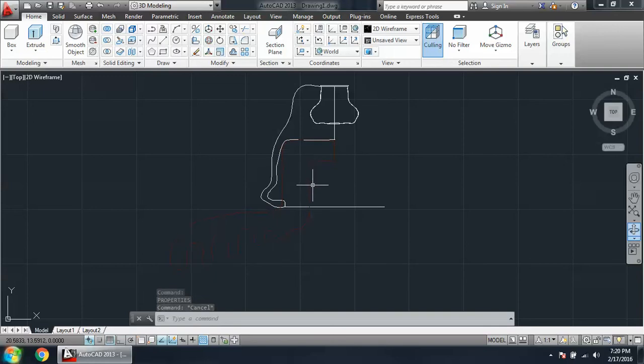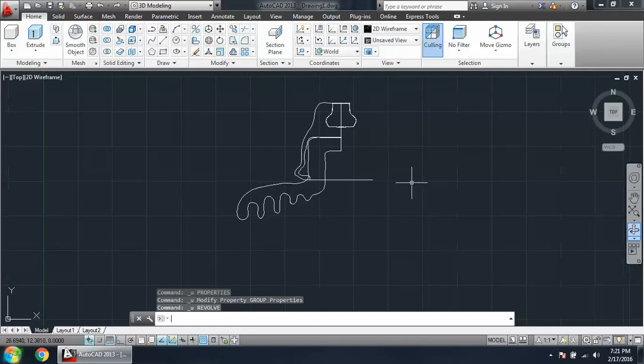The pin we can make is again very simple. We have to make a reference again. Here we make the reference line, proper reference line, enter, and we use the spline command again. Okay, and we may have to adjust this a little bit.